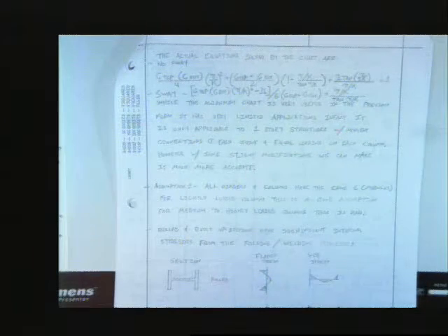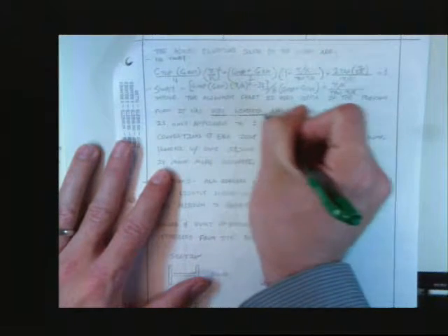While the alignment chart is very useful in the previous form, it has, sadly, extremely limited applications. It can only be used as it's written if every column is the same size, every connection is a moment-resisting connection, every load on each column is the same, and you are only dealing with one-story structures.